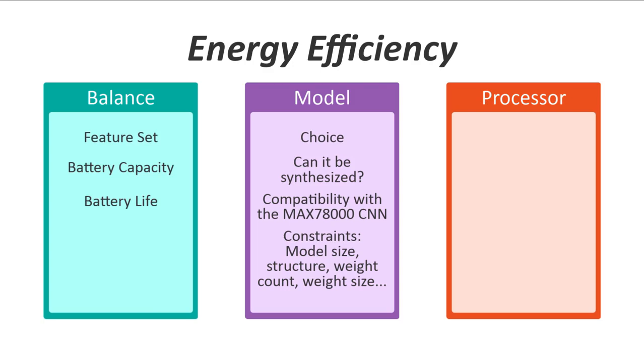The final aspect of energy efficiency is that of minimizing processor clocks, which is of interest to the traditional embedded software folks. This means sleeping where possible, that is, turning off the Cortex via WFI, for example. When it's time to do something with the CPU, then do it as fast as possible. Downclocking the CPU generally doesn't yield the best results.